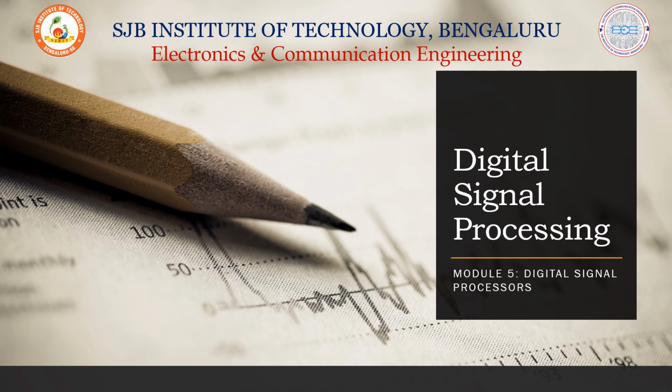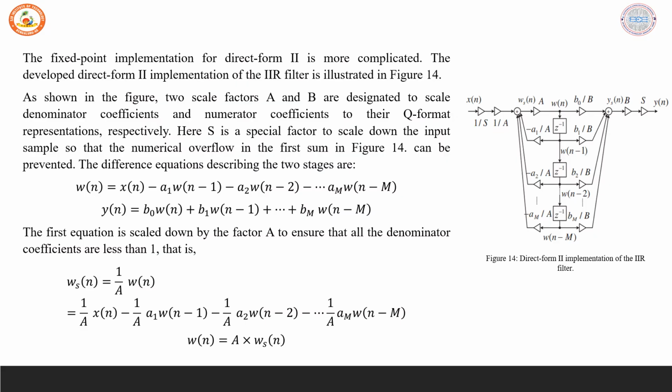In the final part of Module 5, we talk about the implementation of IIR filters using direct form 2 representation. The fixed point implementation for direct form 2 is more complicated compared to that of direct form 1. The developed direct form 2 implementation of the IIR filter is shown in the diagram.